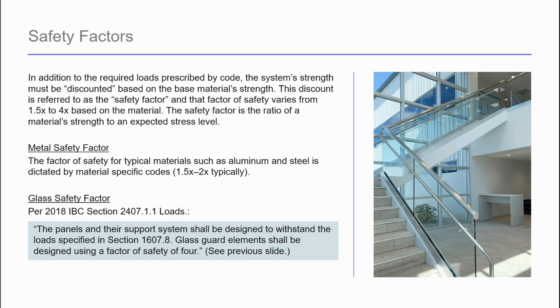It's not easily defined. It's statistically highly variable, but you take a known breaking stress for the glass, divide it by 4, and compare that to the analytical stress. They're the stress that's in the actual piece of glass due to the wind load or the live load. This only applies to the glass in a guardrail system, not other non-glass components. The intent is also not to multiply design loads by 4 in a testing or an analysis. I only mention this because it's a pretty common misinterpretation.